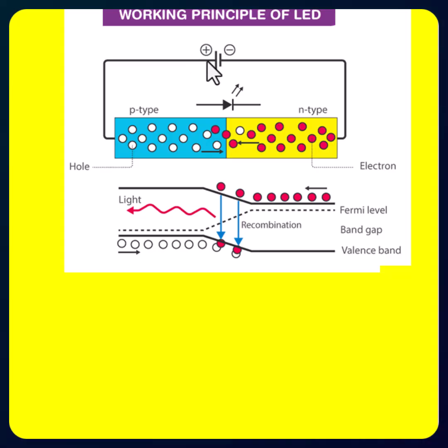If the applied voltage is sufficient, that is 2 volts or 1.2 volts, then the LED is considered as forward biased, and the positive voltage will push the holes that are present in the p-type material towards the n-type material, whereas the negative of the DC supply pushes the electrons that are present in the n-type towards the p region. So at the junction they recombine with each other and energy is released from the electrons, and that energy is in the form of light.